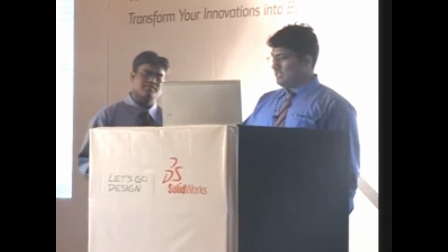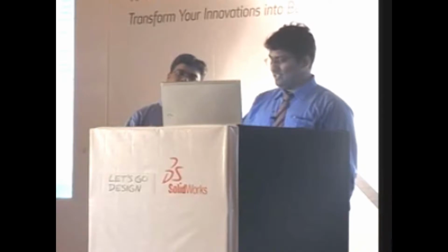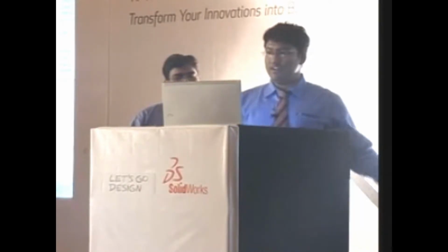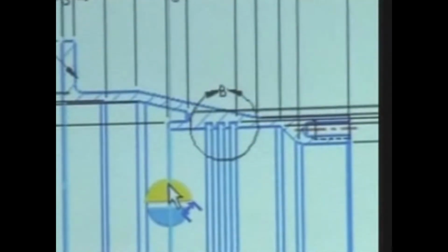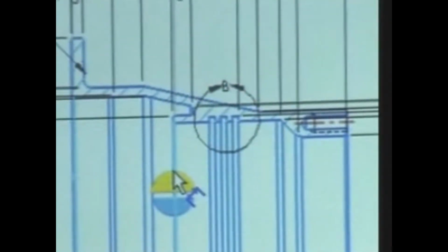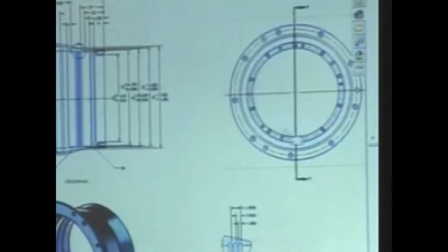Fine then, Ashwin, let me have a question for you. Say, for example, how about if you yourself have a dimension made for this drawing? You can quickly see that the 25.5, which is grayed out, automatically sits in its position. So even I need not reorder the later dimensions which I have created in the drawing itself. I think it's a real productivity tool which we have introduced in 2011.